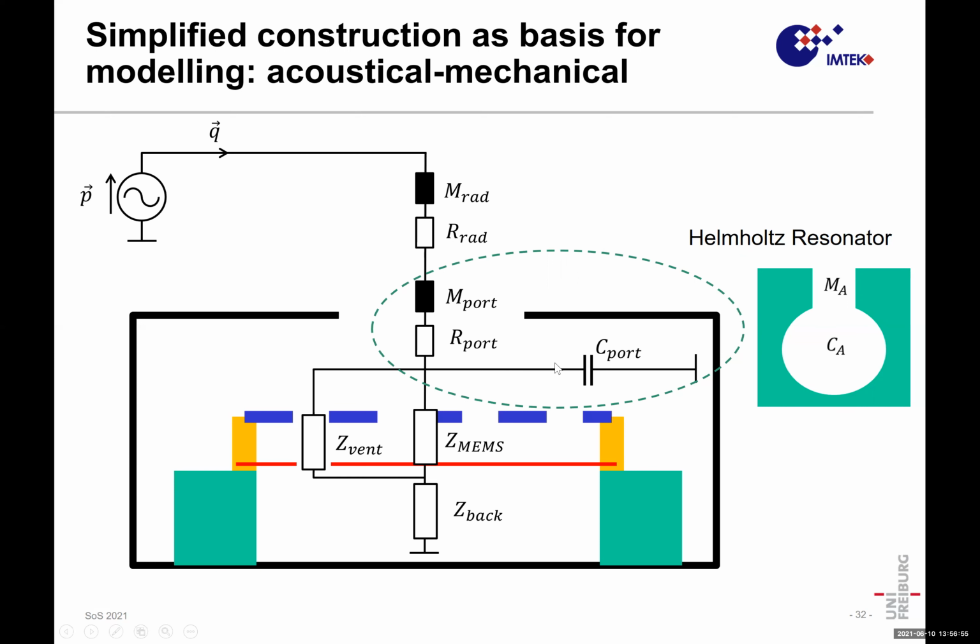And you see we have an acoustical compliance for this front volume, which is going to ground. All acoustical compliances need to go to ground. Then we have the mass inside this hole, and of course we also have to give it a resistance. Since this is a smaller hole, we will have some loss term from there. And then we have already described the sound part.